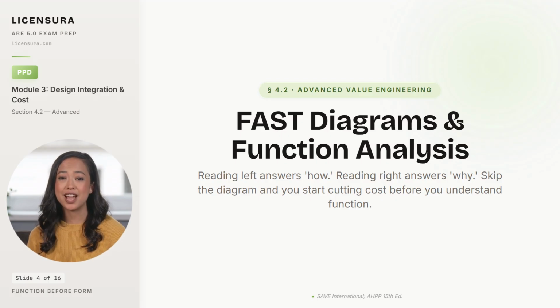You read a FAST diagram left to right to answer how, and right to left to answer why. And that simple navigation prevents the most expensive mistake in value engineering: solutioneering. Solutioneering is jumping to a cheaper alternative before you understand the function it has to perform. The architect who lets that happen owns the lawsuit when the cheaper alternative does not perform.